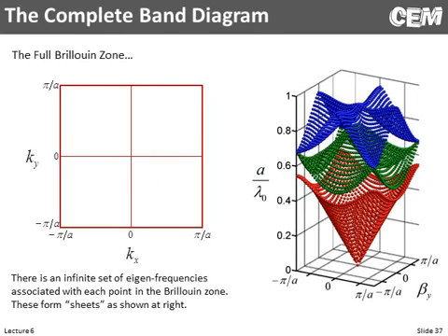So, imagine now, here we have a full Brillouin zone, and we're not going to care about the irreducible Brillouin zone, and we're not going to care about just going key points of symmetry. We're going to go point by point, and we are going to fill in this entire area and calculate the modes and frequencies of every mode throughout the entire Brillouin zone. So this bottom plane is going to be our Brillouin zone, and every combination of beta X and beta Y, we're going to plot our frequencies. And in fact, they would keep going up, but I'm only showing 3.